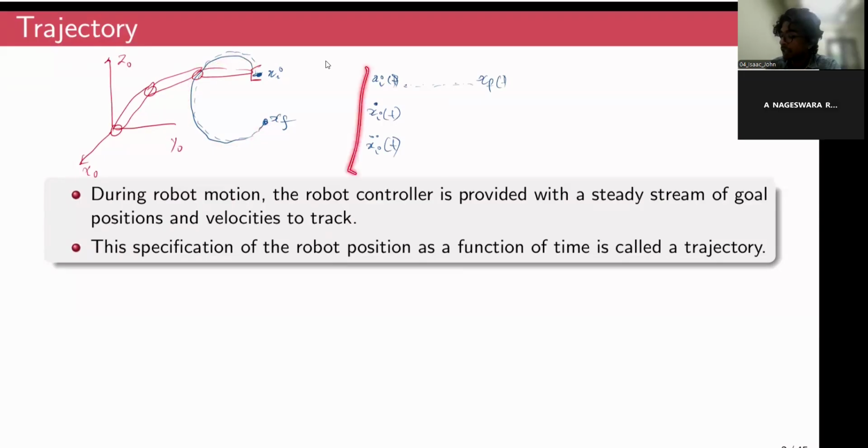And what you essentially do with this model is you plug this model into your dynamic model. So if you can recall, your dynamic model would look something like this. Your torque at the generalized coordinates of a robot would look something like M of theta, theta double dot, plus N of theta, theta dot. This is how your dynamic model in generalized coordinates would look.